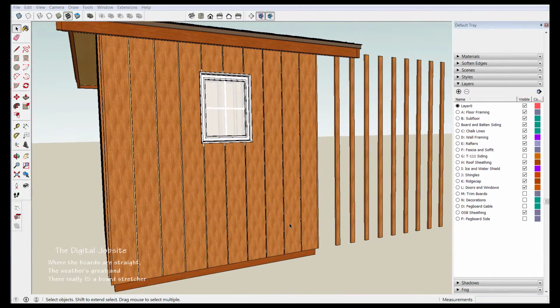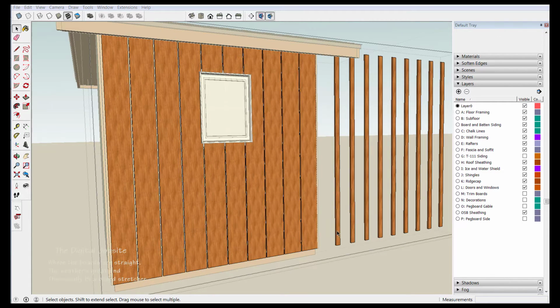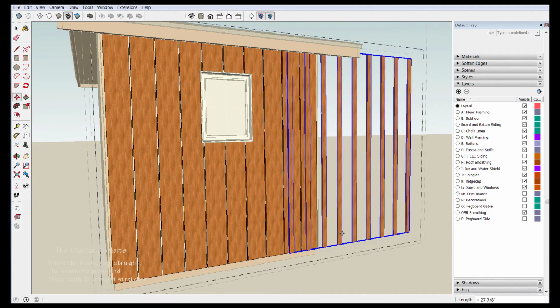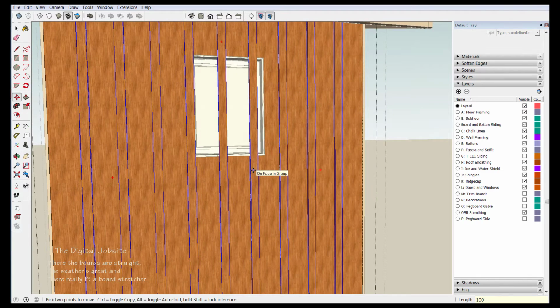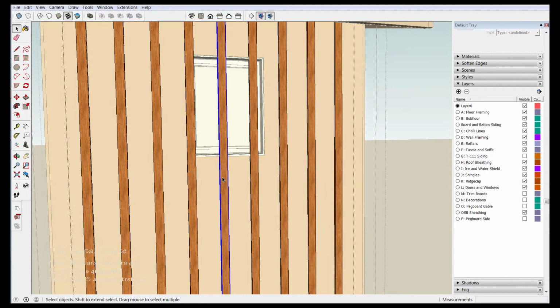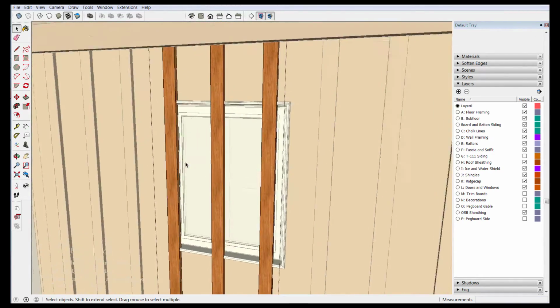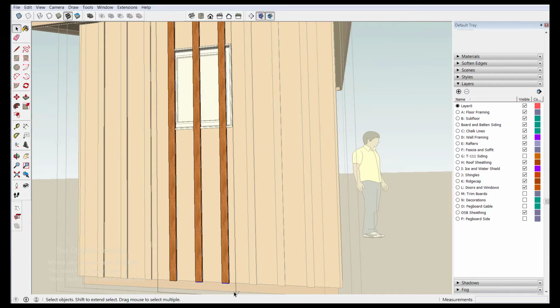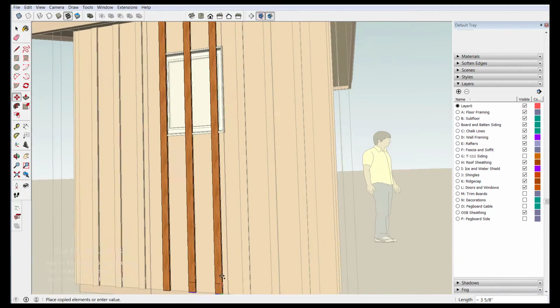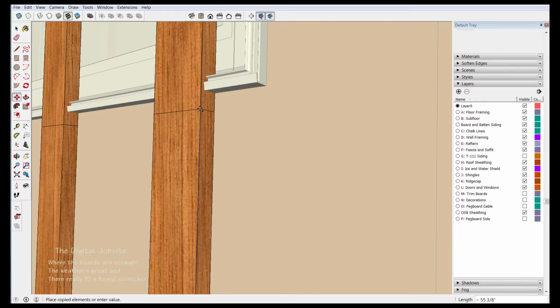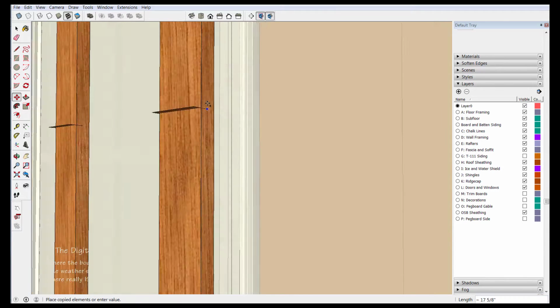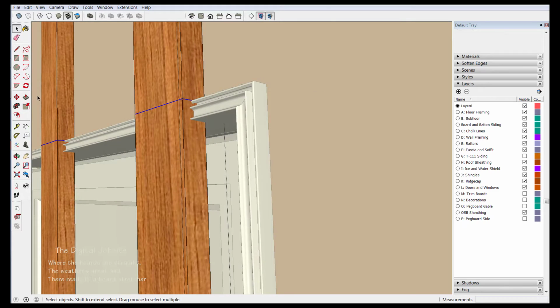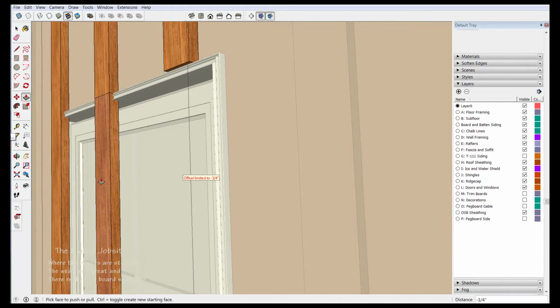So with the siding boards cut out around the window, the next step is to cut the battens. So we'll go into our siding group, go into our side siding group and take the batten group and slide those in to where they belong at 100 inches. And then go into the batten group, take 3 of these battens and explode them and make them a group, and then explode the group so we're not messing with other geometry in the process here. So next I'm just going to take the bottom geometry of these boards with the control key, slide it up in the blue axis, hold down shift, and then click it to the bottom of the window, move and control, take another copy and get to the top of the window. And then we can just take the push-pull tool and push these out of the way to cut them off.